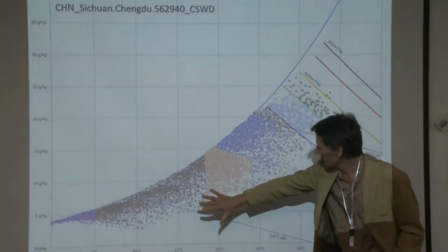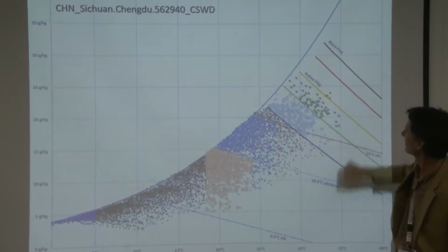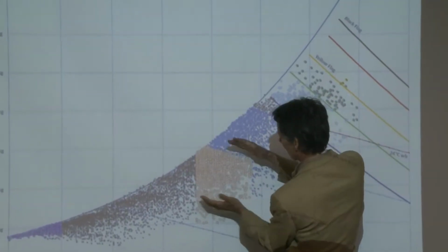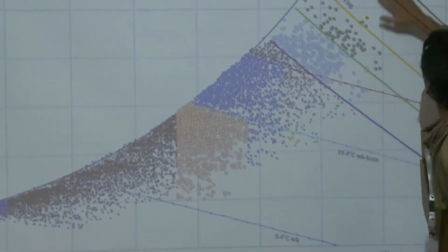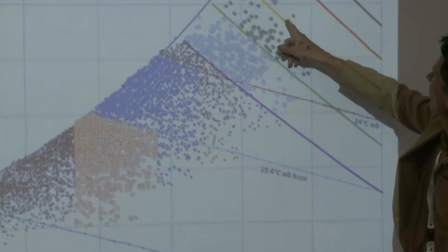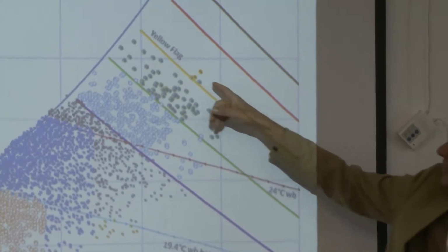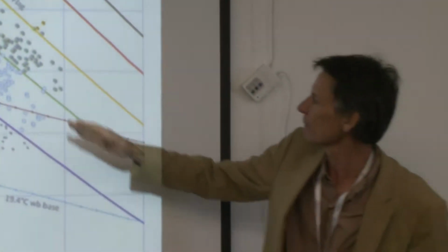If you take the EnergyPlus weather file for there and take those 8,870 points and shade them, here's the sort of classic comfort area. And then here I put these wet bulb globe temperatures. We only got just a handful of hours in that file that are yellow flag conditions. It's really not that stressful. It's a little bit uncomfortable.